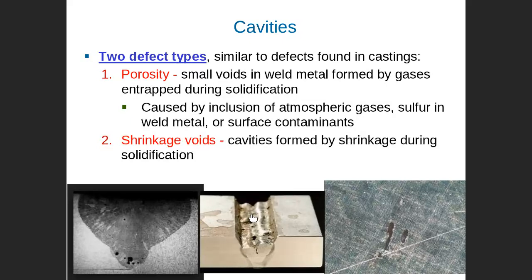So sometimes if you are shielding by gas, gas gets trapped inside and creates this kind of porosity. Or if you're not using the recommended value when you do gas welding or flux welding, if you don't use the correct flux compatible with the weld type, this will definitely lead to gas trapped inside and creating this kind of cavity.